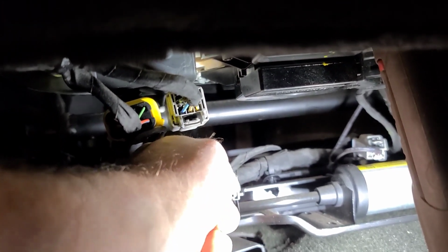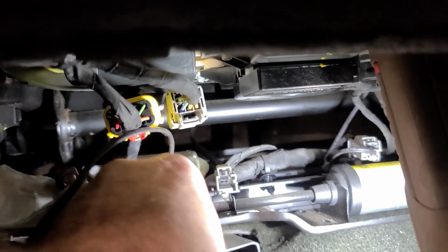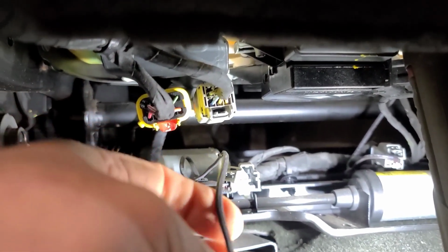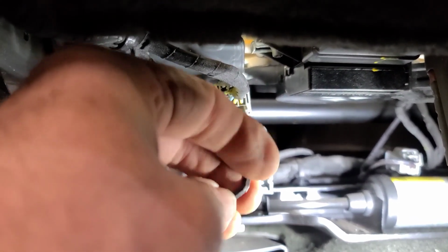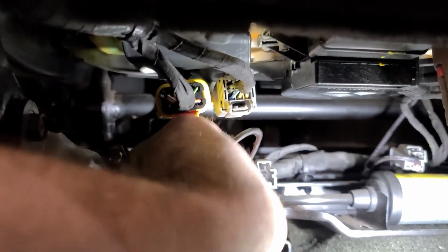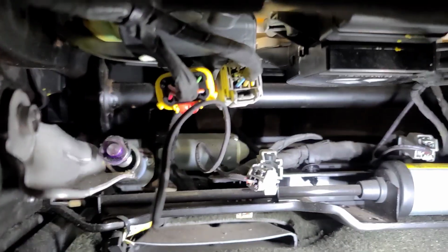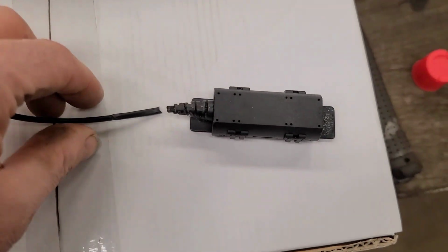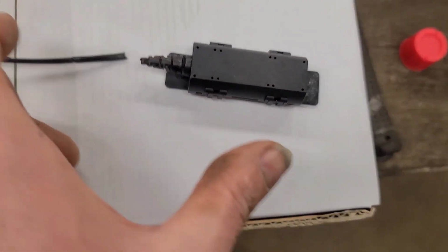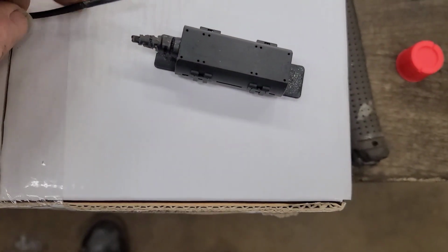So if you go under the back of the seat, lift the seat right up, you'll see this connector right here. This is the seat motor haptic connector, and it's clipped in right there. I pulled the wiring harness out of the seat. You can see it's actually broken in two places. That's just poor engineering. So you can see that when the seat cushion goes up and down, this is automatically going to flex.